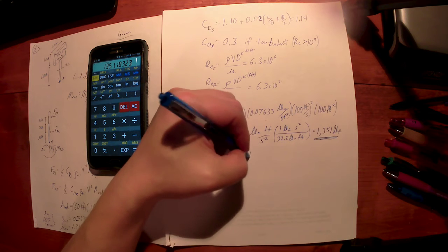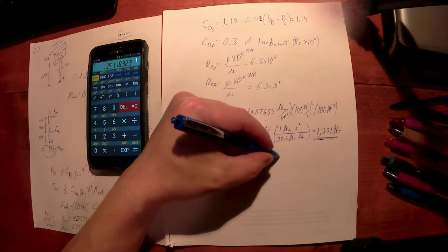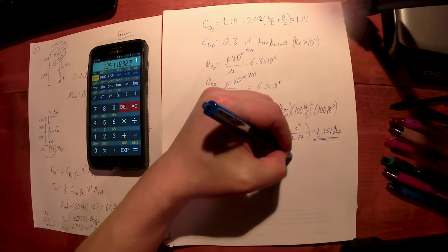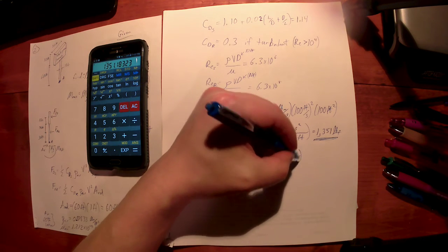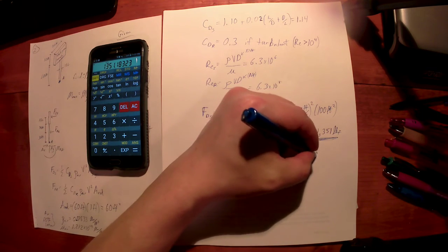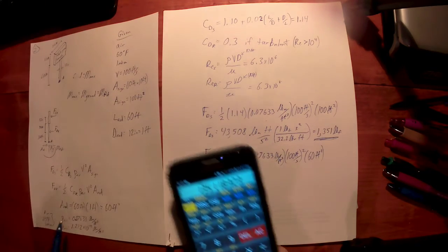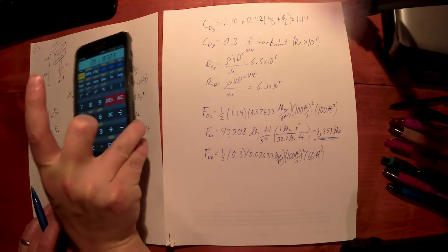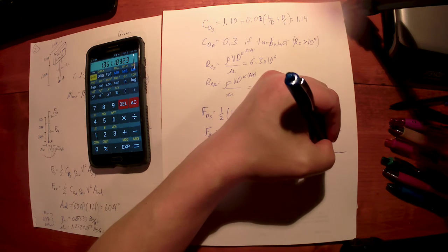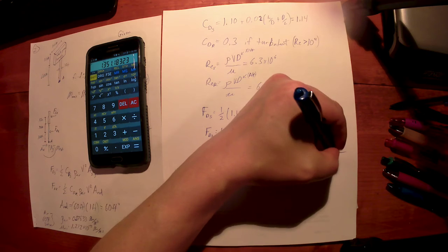The density is the same. It's the same air flowing over it, so it's 0.07633 pound mass per cubic foot. The same speed, 100 foot per second. That's going to get squared because V gets squared. Times the area, we said that is a 60 square foot projection facing into it. Okay? Over here, area of the rod, the 60 foot length times the 1 foot diameter, 60 foot squared. And we know we're going to need this conversion factor to get a number that makes sense, so we'll go ahead and apply that 1 pound force second squared is the same as 32.2 pound mass feet.